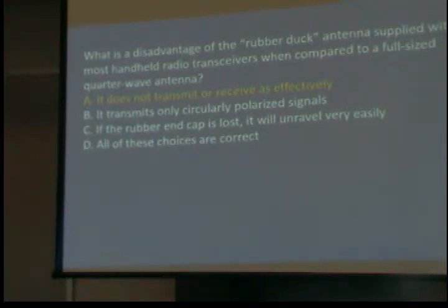So, relative dB gain and loss for quarter, half, full wave, is there an equivalency that's a norm? Yeah. Give me an example: the 19-inch, which is a quarter wave, is 0 dB gain. Anybody who tells you anything else is blowing smoke. Anything shorter than that is negative gain. The rubber ducky might be -3, -6. I'll tell you what my experience has been, it isn't as good as the quarter wave, maybe -6.